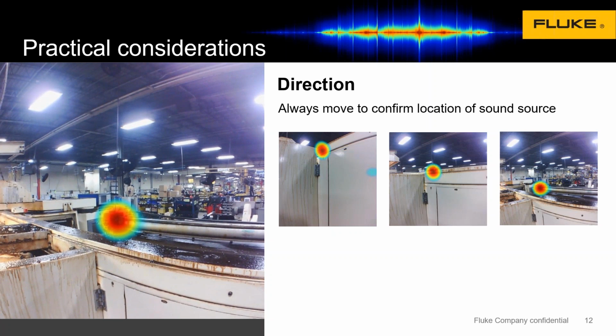That's the other nice thing about this technology: you can tune the frequency and ignore a vast majority of the other things that are going on. You don't have to wait for the quiet Saturday morning and spend extra money for weekend hours to have somebody going on a snake hunt finding air leaks or gas leaks because all the production's shut down. You do this right in the middle of production.